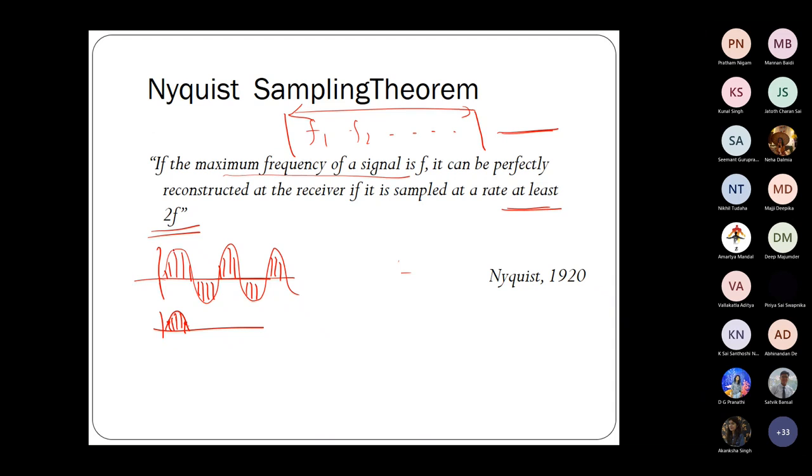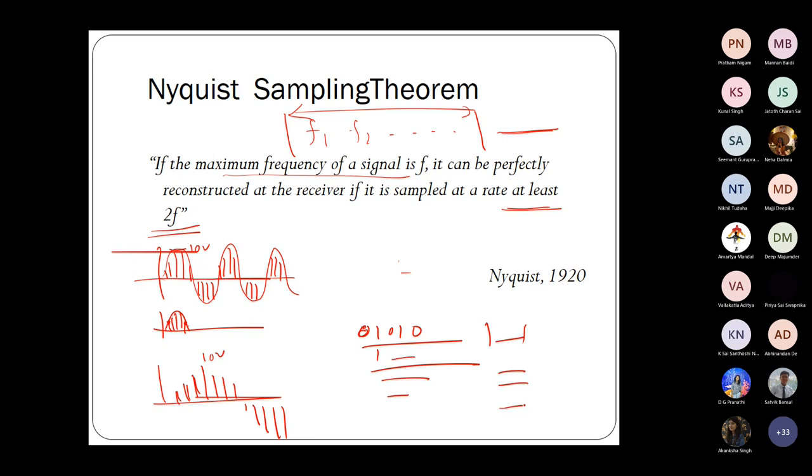So if I do this for this, let's say this peak value is 10 volt, just suppose, I'll get different things. So basically I will get values like this, time versus voltage values basically, minus things and so on. All right. So I got a discrete signal, no longer a continuous signal. Now that's not part of sampling theorem, but if I want to digitize this, basically I look at each of these values. So maximum is 10 volt. I say I will take a 4 bit. So my 10 volt will become 1010, and then appropriately I will code the other ones, and then I will transmit this. On the other side, I will take out these 4 bit patterns, and then I will reproduce the values. I'll get a signal like this, and then I will kind of regenerate the signal from there.